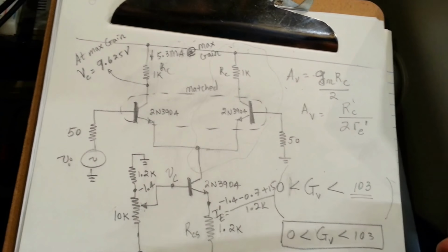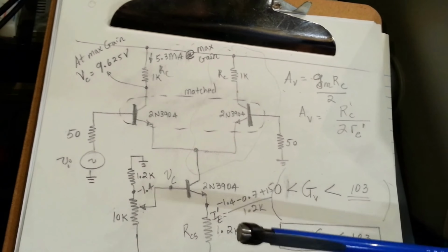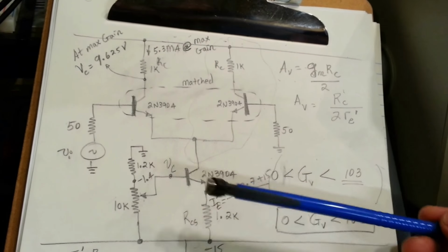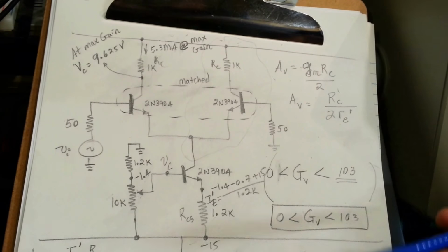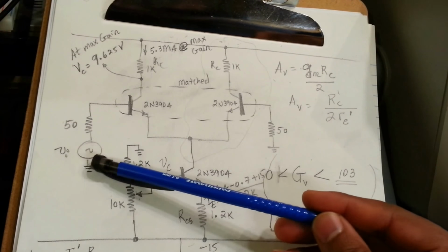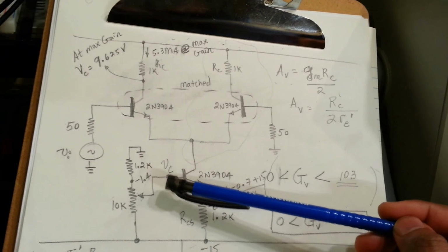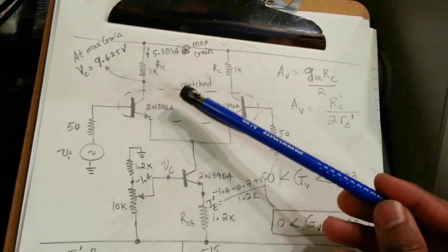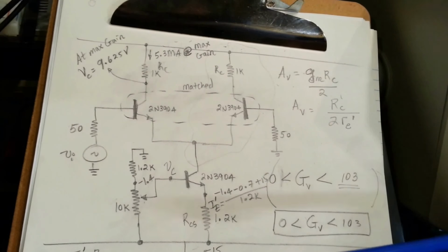And also it can be used in AGC type circuits, automatic gain control circuits. For example, you could use it in automatic volume control in a power amplifier, depending on the input signal. You can sense that, and you can vary the control voltage here, and you'll be able to control the gain of the amplifier, which means you can control the volume of the amplifier.